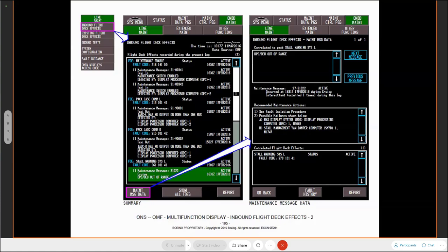It's going to give you the warning light because when you put the pump on, you want that light to go off. So when you put the pump on, the light goes off, the fault code's gone. But if you put the pump on and the low pressure light stays on, then it's going to generate a maintenance message. And now you've got a fault code and a maintenance message, it correlates the two together, bang, it's up the top of the list. So you can have all different mixes and combinations. You don't always have to have correlated maintenance messages. This is just sorting those messages in an order of priority, the highest ones first.